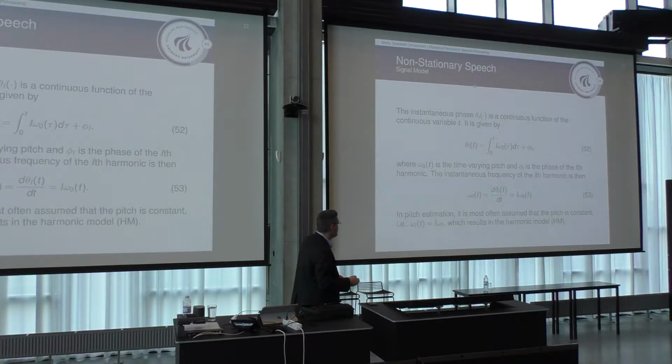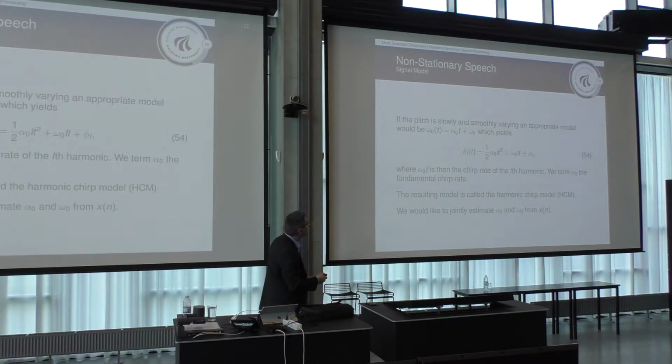Often in pitch estimation, you assume that the pitch is constant for like 20 or 30 milliseconds. So you're essentially saying that this does not vary with t here, pitch does L times omega 0. So you're saying it's changing from this level to that level and then down to this level again, which I think everybody agrees is not the case. But this is what gives you the harmonic model.